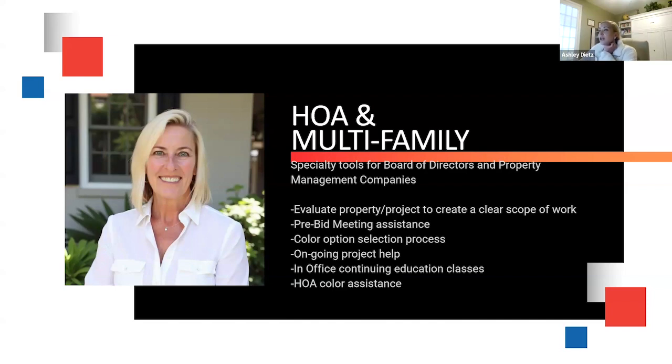Here's one. What is your recommendation on painting aluminum rails with some corrosion? I would say let's address the corrosion first. Yep. So we're hitting that clean, dry, dull principle. And again, results vary. There could be a product that I think will be awesome, but then I get there and look at it and realize there are other factors here that could alter that decision. So I wish there was a one and done, and there really isn't, nor do we want it to be. We want to make sure it's specifically tailored to the individual project.